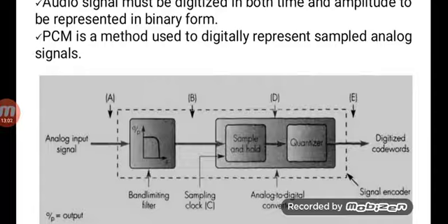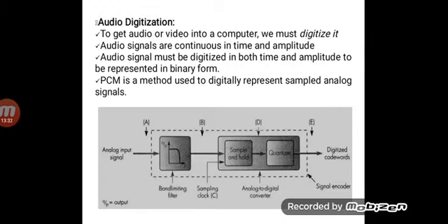so that the quality will improve a lot, and you can easily convert that signal back into the analog domain when you need to feed it to a loudspeaker. To a loudspeaker, when you need to apply a signal, that has to be in the analog domain only. So you need a conversion from digital to analog again. To get that conversion, you need to use a higher sampling rate as well as higher quantization levels